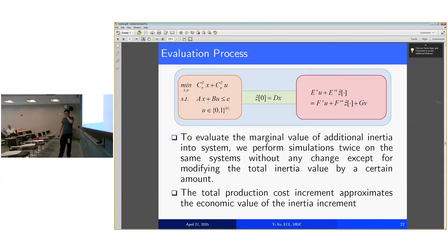So here, one more question to you. Do you have a set of those constraints for each possible contingency you would consider? In this problem, I only consider one contingency, the sudden load increase. And the reason is we do not expect to find all the constraints, all the n-1 security constraints, in the simulation, because it would make the problem too complicated to solve.